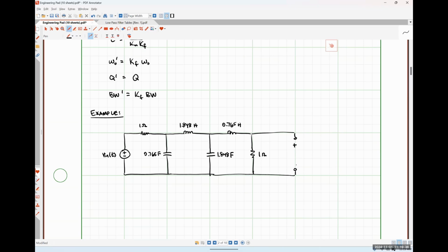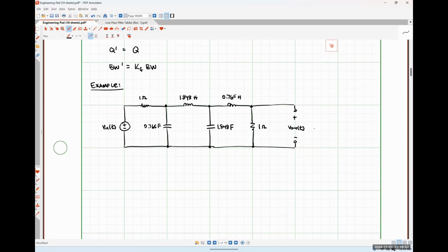So this particular system, or filter circuit, like I said, it's a fourth order Butterworth filter, meaning it has 4 different energy storage elements that can't be combined into any simplified energy storage elements. And this circuit was designed to have a cutoff frequency, so let's call that omega C, equal to 1 radian per second, for a matched resistance of RS equal to RL equal to 1 ohm.